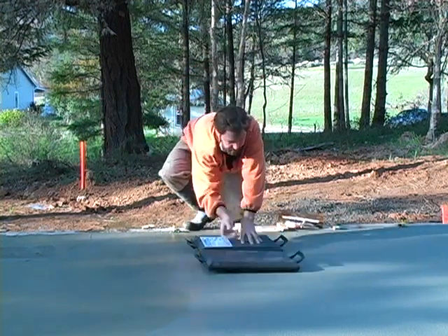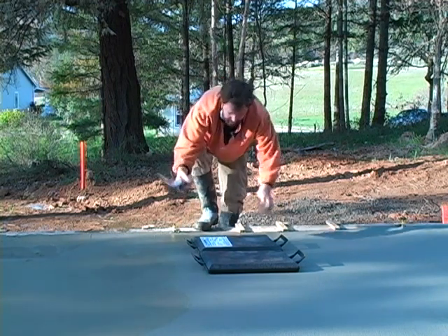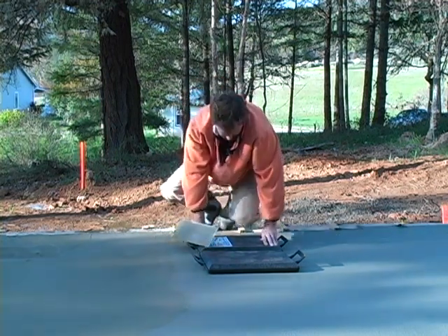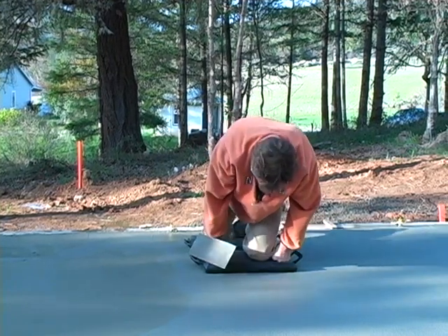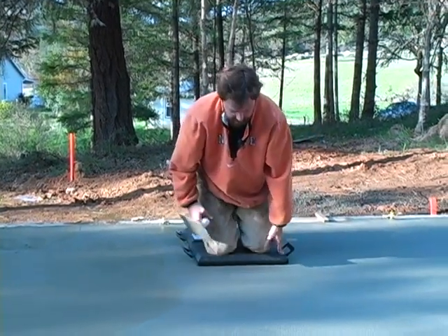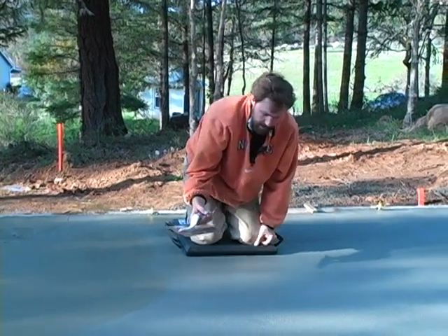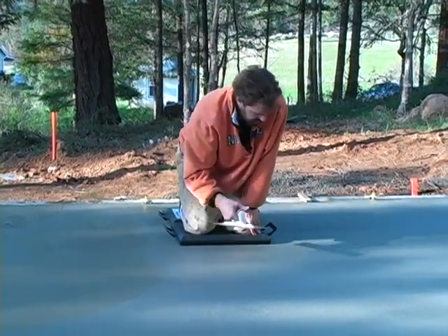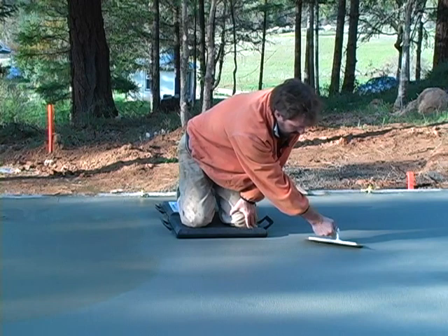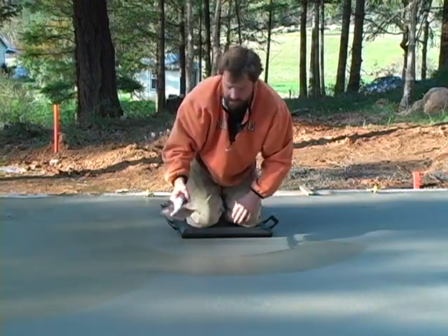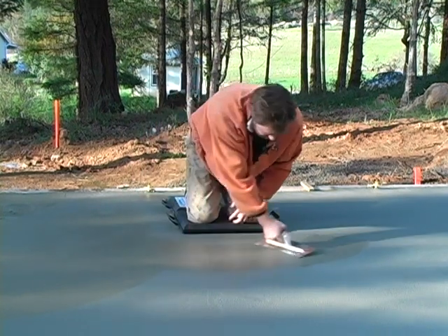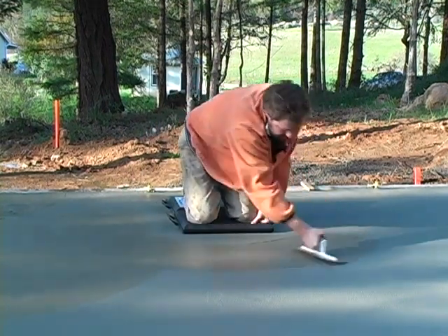far enough that you can reach out to the middle, and because they're wider, they're not really taking the weight of your body on your knees. You're taking it spread out over the larger surface area so it doesn't leave a dent. Now when you get out to finish it, just using a regular steel trowel, you want to keep an angle on it and push down on the back side. So whichever direction you're moving, you're pushing down on the back side of the trowel.